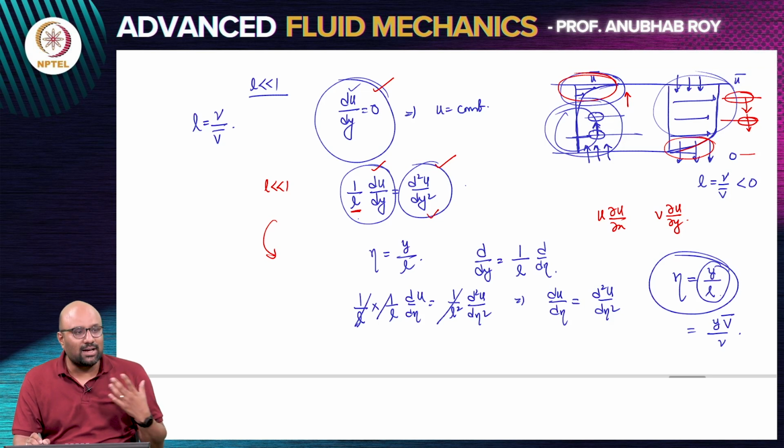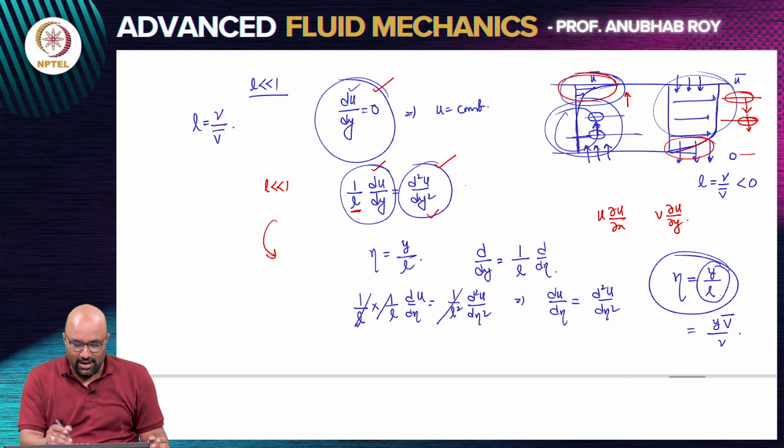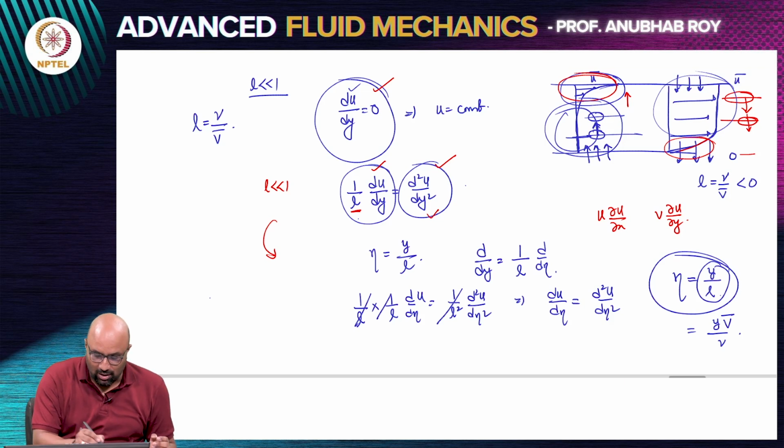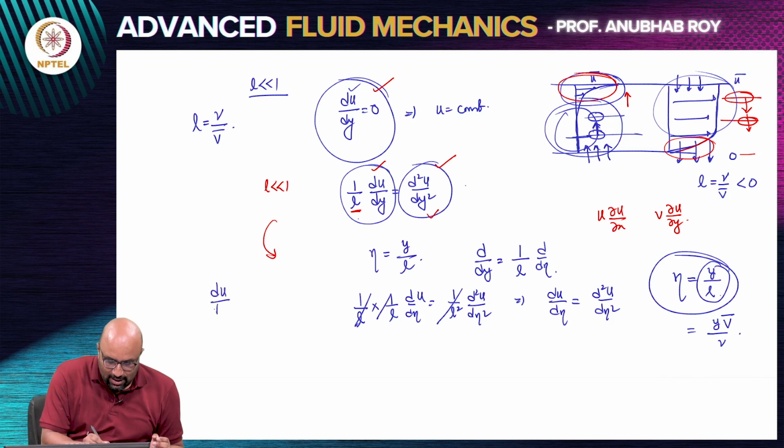And this is basically your introduction to a topic that will come in some time, which is boundary layers. You are already seeing through this very simple problem that advection and diffusion cannot necessarily be seen as separate. There are regions in the problem where, if you think of L being very small, it means that du dy is equal to L d square u dy square.